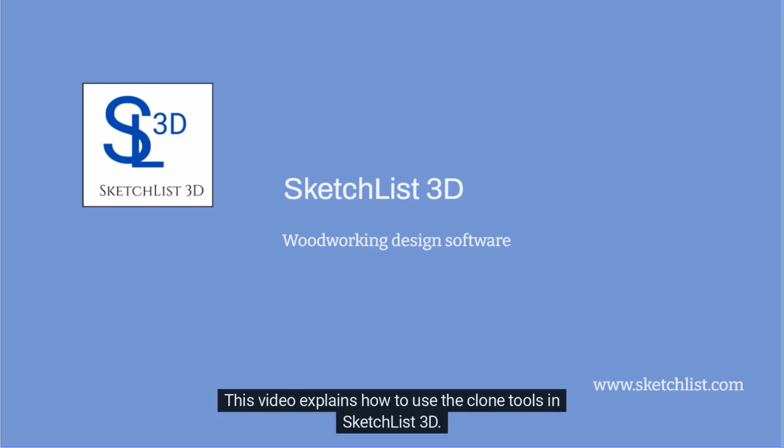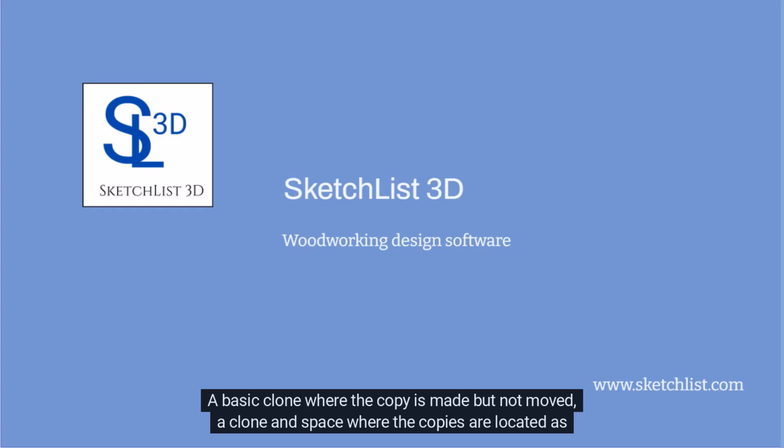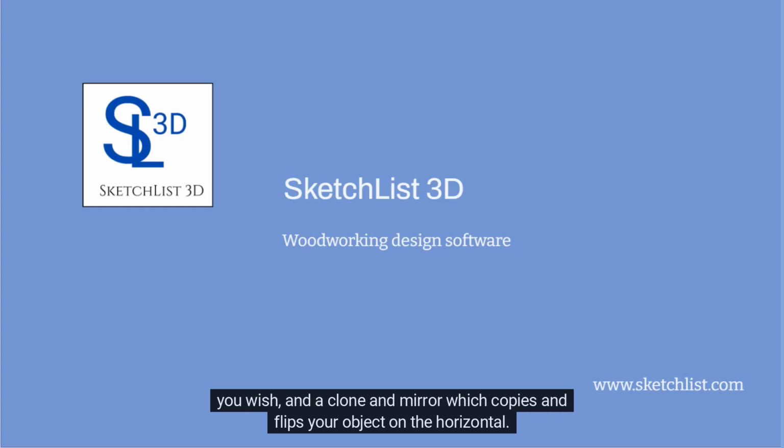This video explains how to use the clone tools in SketchList 3D. A clone is a copy of an existing object. There are three types of clone. A basic clone where the copy is made but not moved, a clone and space, where the copies are located as you wish, and a clone and mirror, which copies and flips your object on the horizontal.